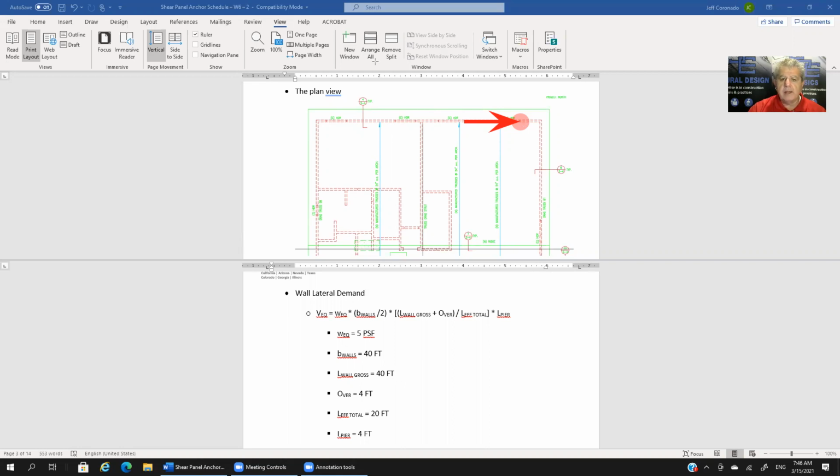With that, we are now looking at this expression. What we've got is that this earthquake force V is equal to W earthquake, which we've already covered. That gets multiplied by the width between the walls. By that we mean the distance between the wall lines.